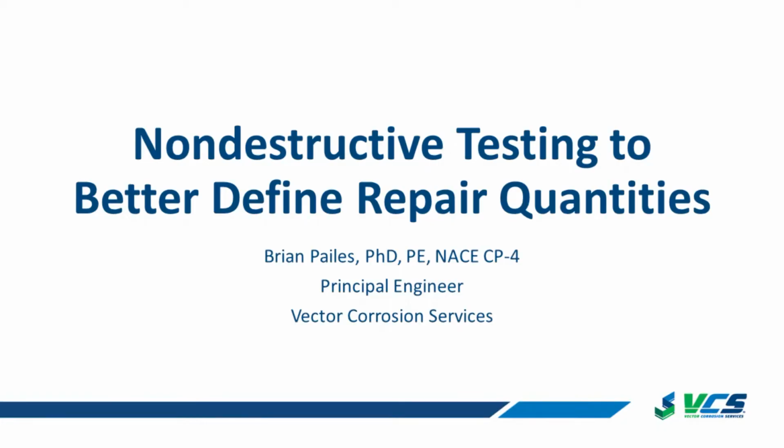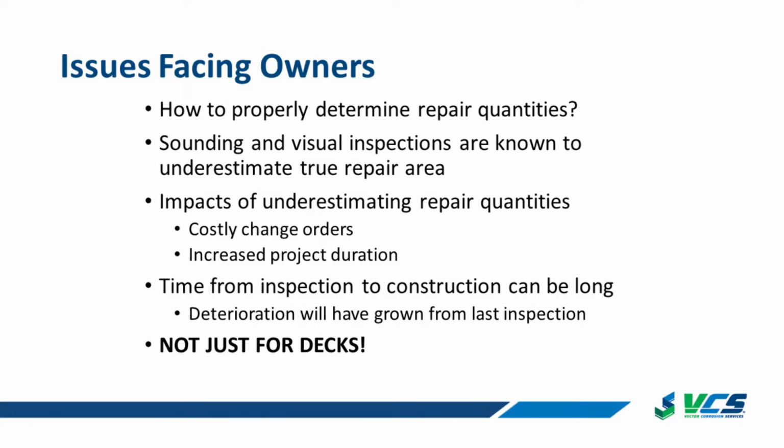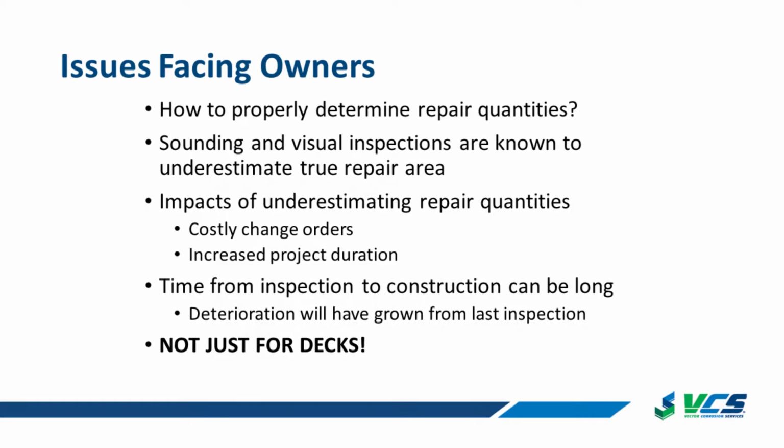So today I'm going to talk about non-destructive testing to better define repair quantities for reinforced concrete structures. A major issue facing all the owners here in the room and throughout the country is how do we properly define our repair quantities for construction and the repair. Sounding and visual inspection are tools that we commonly use throughout the industry, and they're very effective, but they're known to underestimate the true total quantity in the end.